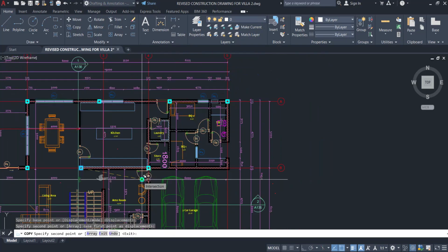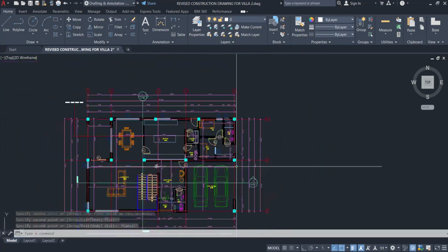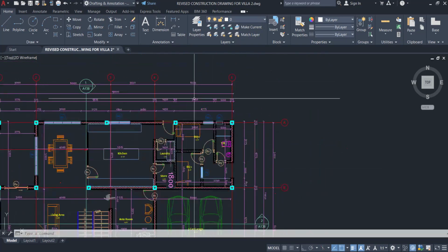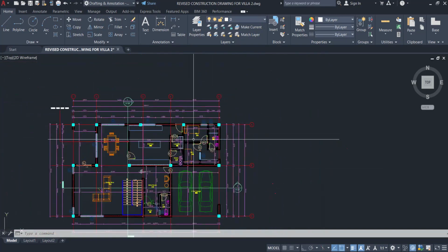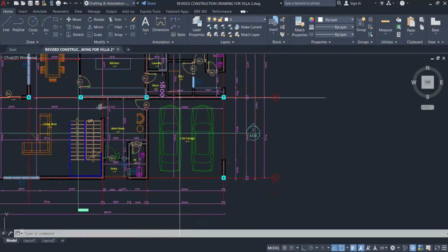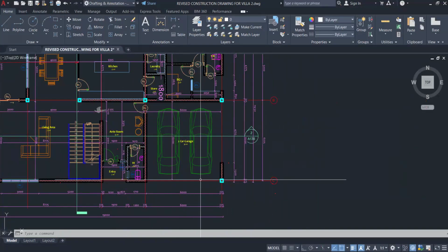So if I put a column here, and then I put another column at the last edge here, you can see that this column and this column are long. So you can just break it, even though it's 6 meters, for economic design it will work. Another reason why I wanted to break it, by putting a column in the middle, is because this place is a car garage.